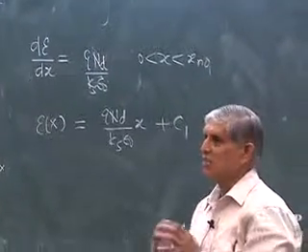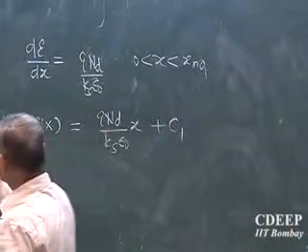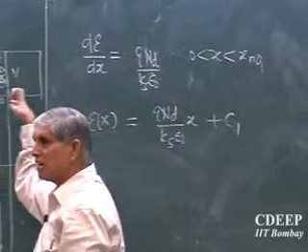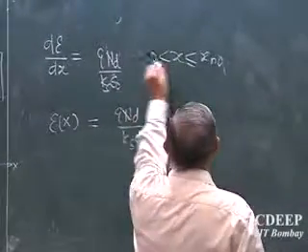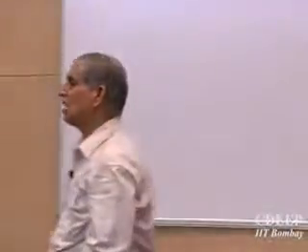One, of course, at x equal to 0, it is E0. But another thing I am looking at is x equal to xno; beyond that, I don't see any charges. So on the inside, what are the charges there? Charge neutral. All semiconductors are charge neutral till you apply something to make it non-equilibrium. When there is charge neutrality, what is the field there? There is no field because there are no charges there.